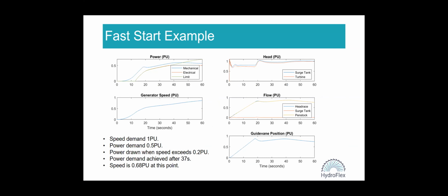Because this is a further freedom in space for the generator, which normally is not considered: the generator and the turbine generating power at not nominal speed. So is there any investigation of what this will inflict on the generator and on the turbine? Because I guess the hill chart will become very complicated.